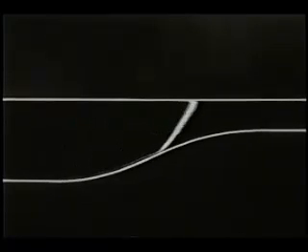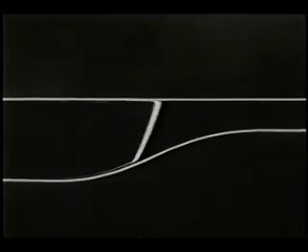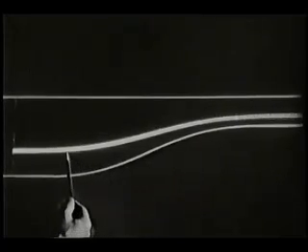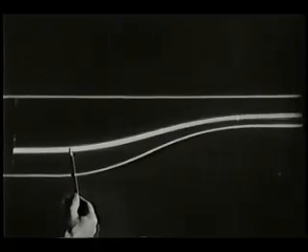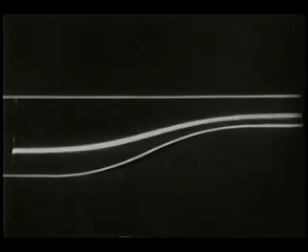Here, near the beginning of the curve, the increase of stream tube area between the streamline and the curved wall shows that the velocity on the curved wall at first decreases. Near the end of the curve, the stream tube area reaches a minimum before once again increasing slightly. This minimum corresponds to the point of minimum pressure.